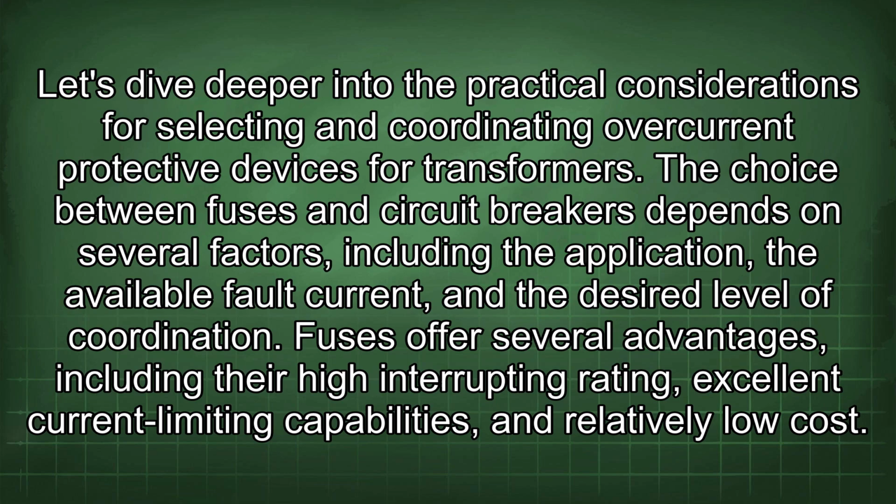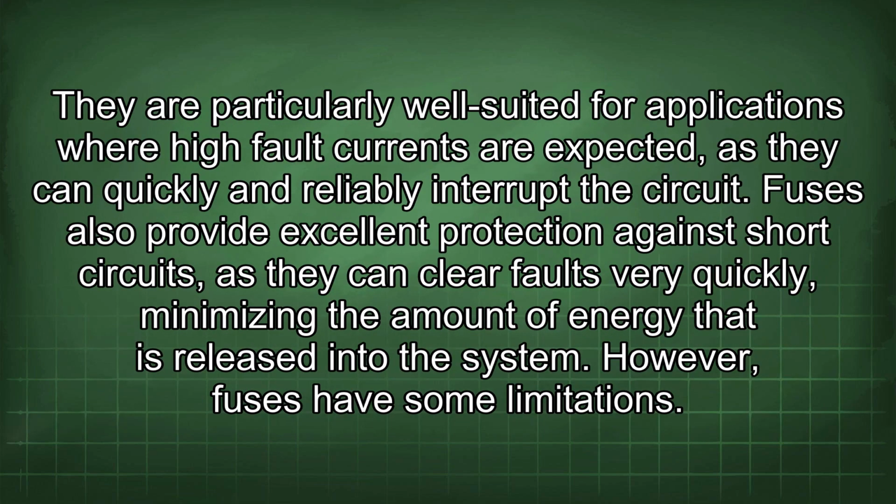Fuses offer several advantages, including their high interrupting rating, excellent current limiting capabilities, and relatively low cost. They are particularly well suited for applications where high fault currents are expected, as they can quickly and reliably interrupt the circuit. Fuses also provide excellent protection against short circuits, as they can clear faults very quickly, minimizing the amount of energy that is released into the system.